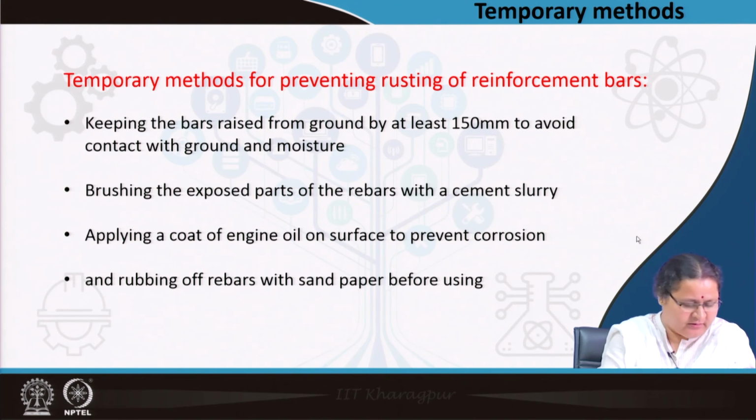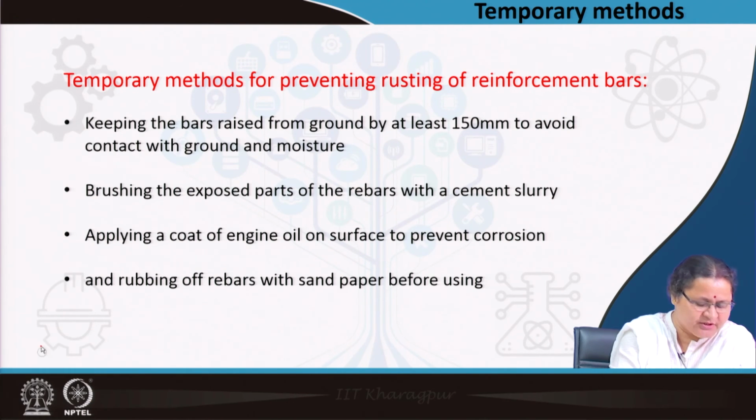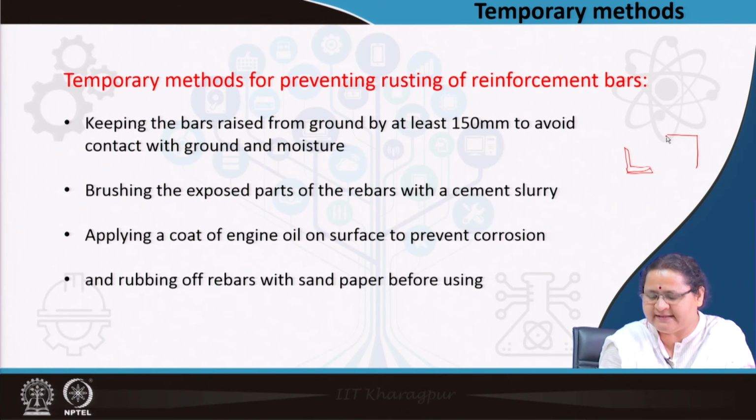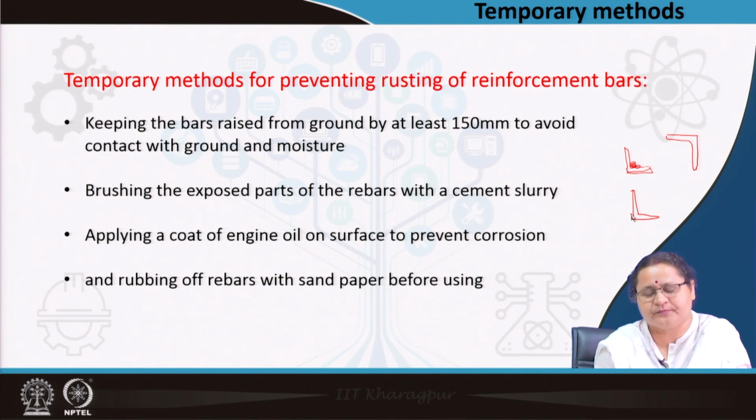You have also seen in our rolled sections, we had seen the angle sections. Now, it is advisable to place such sections on structures in this direction, so that water accumulation does not happen in these portions. Water is not supposed to get accumulated because you have a slope. But yes, some dust particles may come here which can retain the moisture or the water and allow rusting here. So, if you use such T sections in this direction, you will always get the advantage of the water getting drained out.